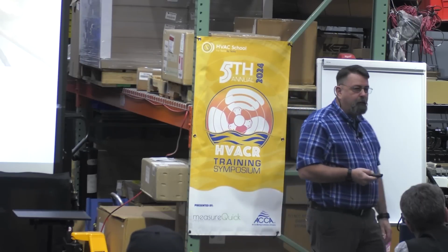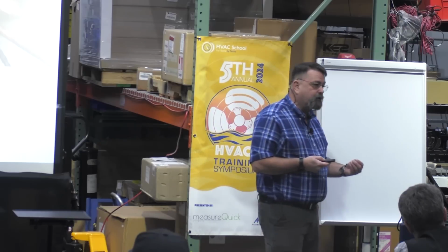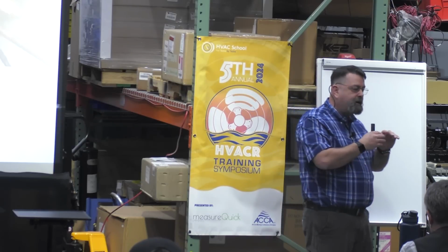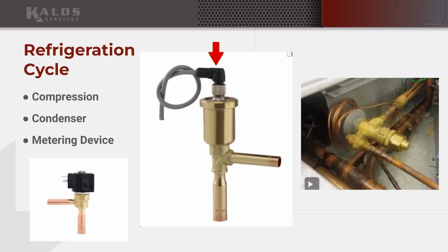This is a bipolar motor. We're seeing these really heavily in refrigeration in a lot of different places, right? My mechanical expansion device has an orifice, and it's got a pin, right? The pin plugs the hole, and that makes no flow, and then I just open that pin up, spring pressure and all that. It allows more refrigerant to flow through. Well, I'm just making a hole bigger or smaller.